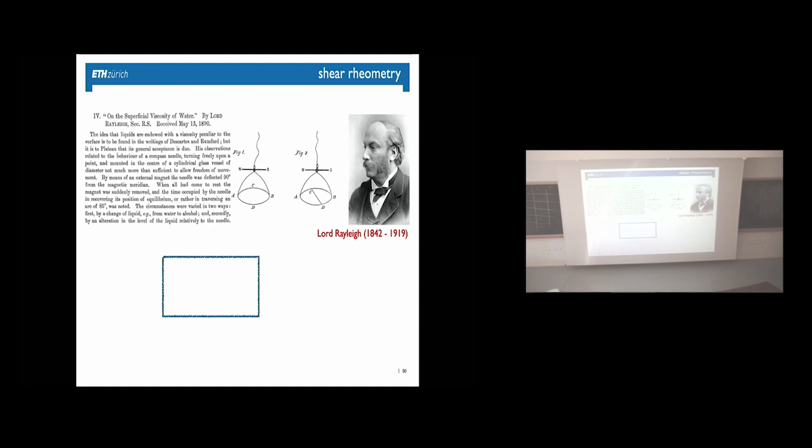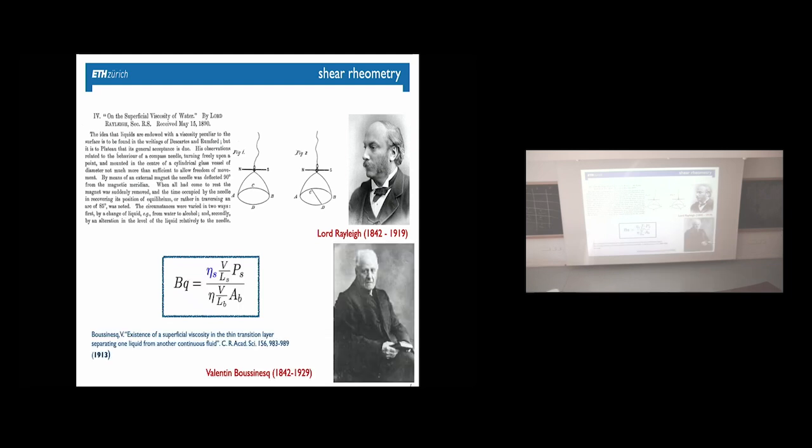It means that when we try to measure a stress boundary condition, an interface, we don't want to measure the bulk, right? So we want something that's thin and long, like a needle or a ring, and that's what Rayleigh proposed. And there's a French mathematician, Boussinesq, who was first in Lille, then in Paris, who then did the first mathematical analysis of it and showed how bulk and interfacial contributions can then act as stress on an interface. And so we now call a non-dimensional number the Boussinesq number that says that the stress from the surface must dominate the stress from the bulk.